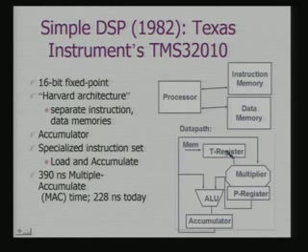So, you have a dedicated multiplier, and a separate register where you are getting the data from the memory. The output of the multiplier goes to something called a P register, which can be used with the ALU to get the accumulated result in the accumulator itself, and that can be put back again with the multiplier if required. You can realize that this organization of the data path is primarily to facilitate the multiply and accumulate operation, which is the key operation in any filter implementation, and we have seen how it is critical for FIR filters.